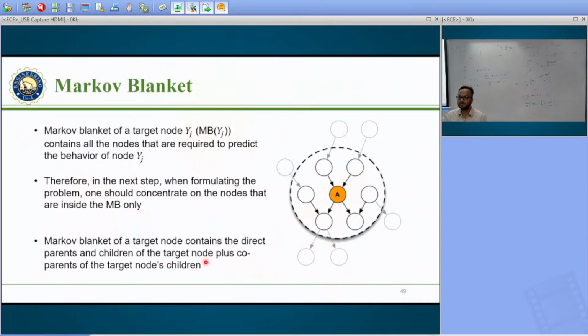Wireless sensor networks. So let's suppose you wanted to keep multiple sensors, like in a jet engine. There you use sensors at multiple locations to measure the turbine temperature and the inlet temperature of the fluid. How many sensors you want to use and where to place them is a critical question. So if I know the network structure of these variables, then I can reduce the sensors. If I know this information, I need not put sensors around this particular location, only around these particular variables, because they have a good amount of information, and for the remaining I don't need any sensors. So you can reduce the dimension.